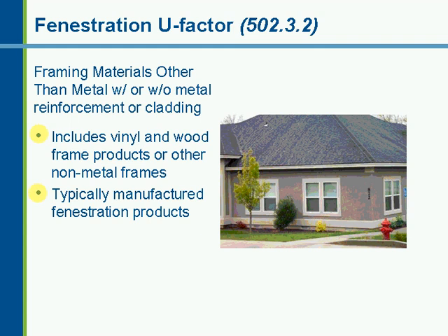So in the example shown on the right-hand side, the small office building, you can see vinyl framed windows being used in this. And this is typical in a lot of small medical offices, just small office buildings, and small residential or low-rise commercial construction of fairly small square footage. From this standpoint, the U-factors are a little bit easier to meet, and really you get down into the low-E window requirements after about climate zone 5, where the requirement goes down to 0.35 U-factor.